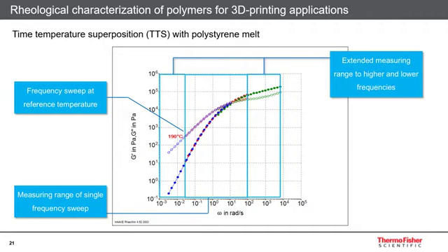The viscoelastic behavior in this range is strongly driven by the molecular weight distribution of the polymer. At the highest frequencies, the sample behaves predominantly elastic, with G' larger than G". Here, the polymer's behavior is dominated by fast relaxation motion of the shortest polymer chains.